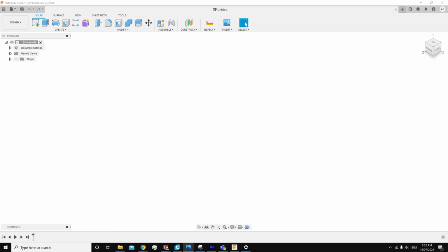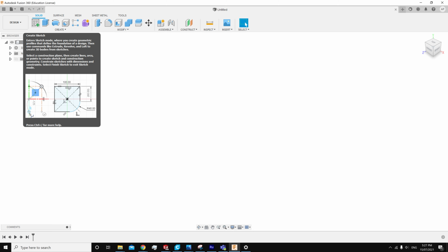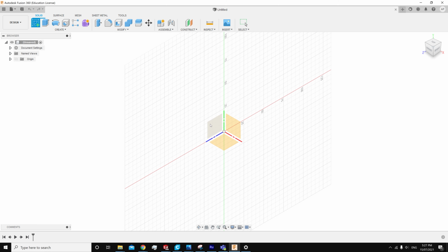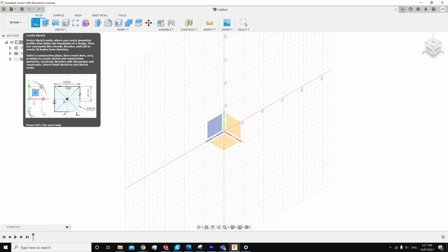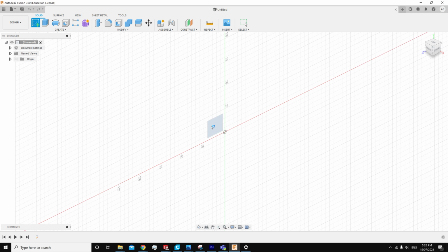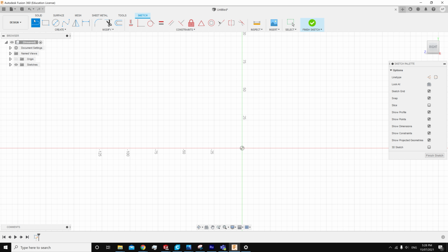But I'm just going to leave this as a non-tapered stool. So I'm going to make this stool about 500 millimeters in height. So the first thing I'm going to do is click Create Sketch and then select one of the planes. I don't want my leg to be any thinner than 70 millimeters. So whenever I'm drawing a line, or this is going to be a joint between the two pieces, I'm still going to set this as 70 millimeters.